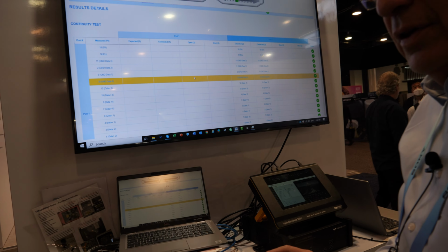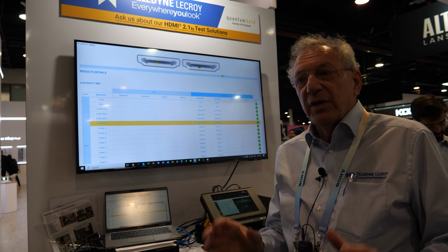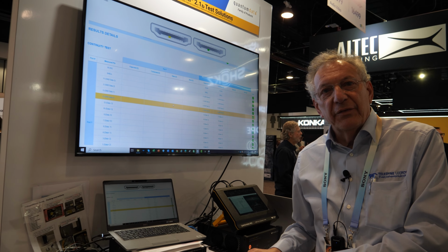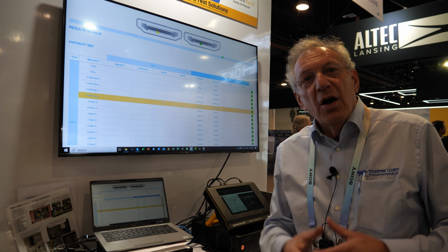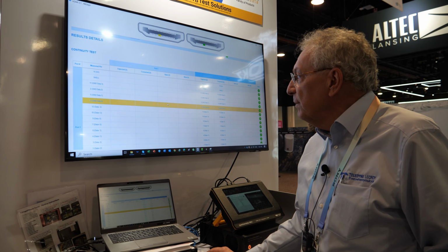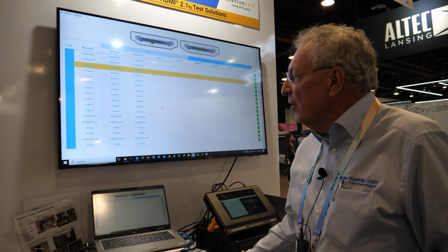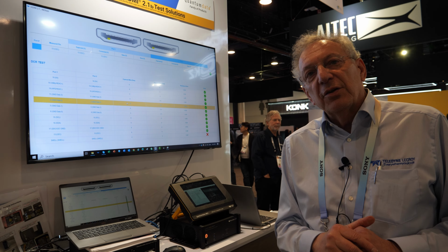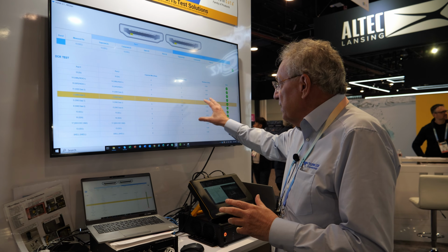You know, this is really fundamental because, remember, the cable is going to a very expensive device. Any small issue that you may have on the continuity of the cable can lead to big trouble on expensive devices. So you need to make sure that everything is fine. Even more, we have the measurement of the resistance for each of the pins of the connector. Even in this case, it's very important.